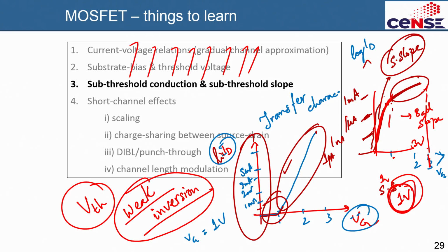If you can go by this order of magnitude change in current, that is the on-off ratio, the digital 0 and 1, if you can change so many orders of magnitude of current at very low voltage, say 0 to 0.5 volts, that means your battery has to supply lower power, which means your smartphone battery will last longer. You have to charge it less, right. It will be very convenient.